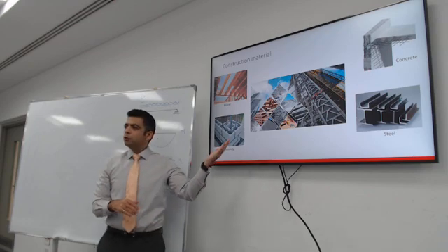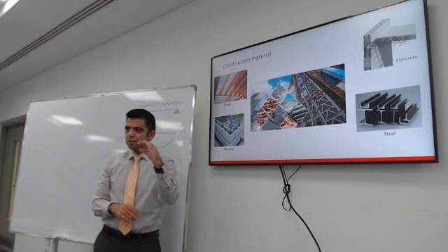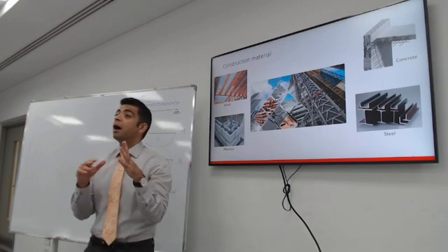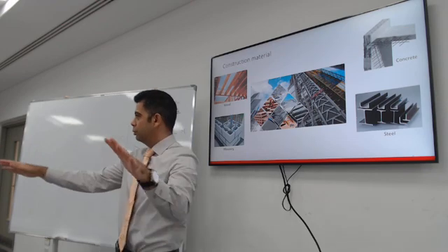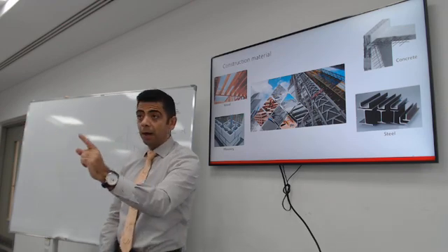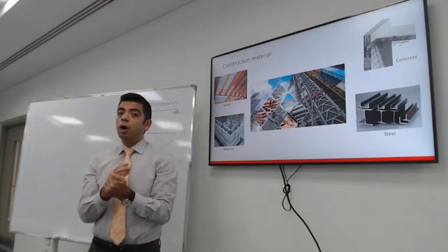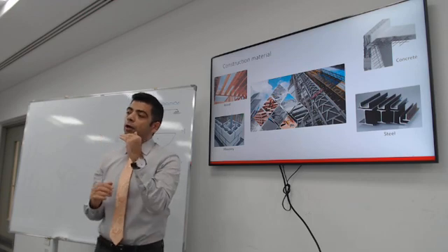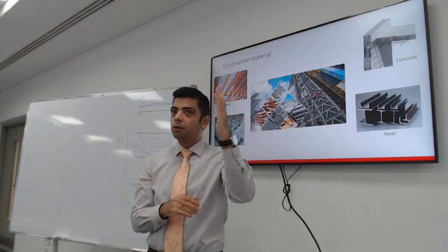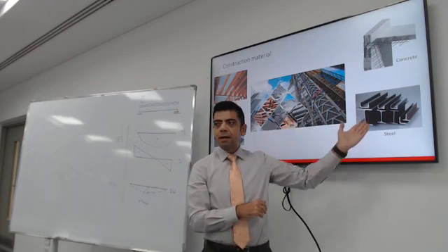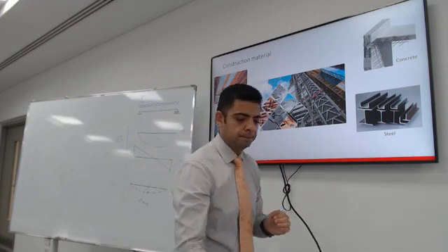It's very common to use it as a partition wall, like those red blocks that you see that we use in buildings. Typically, we don't use them as a structural element. We just use them to separate this big room into 2 rooms. But you can actually use them to build an actual building without concrete, but you cannot go as high as concrete structures. If you're building a skyscraper, you obviously need reinforced concrete and maybe steel. Those are for smaller buildings.